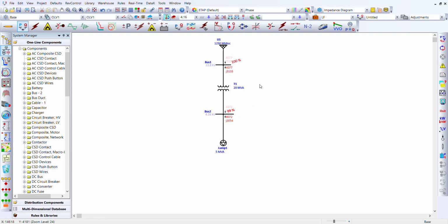So next, active and reactive power flow. Now this, as we all know, this is the real and this is the imaginary. This is where we can toggle options to show the unit we want to see. Now you can choose your apparent power. This is only apparent power, kVA, or you can choose your true power and reactive power, which is kilowatts and kVAR, or you can just choose kilowatts or anything you want. Basically, you can see everything, and that's why we carry out load flow analysis.